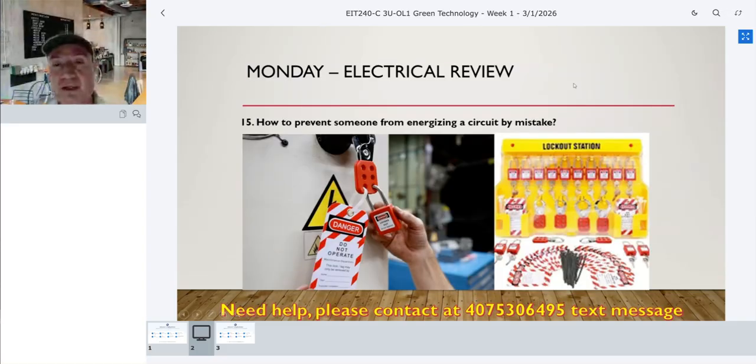Okay, another important thing, and also very important because safety is number one for us. My recommendation when you're working with electricity, guys, please use your personal protective equipment, and if you're working on some machine or some special area, don't forget to lock out, tag out. This is the question: how to prevent someone from energizing a circuit by mistake?